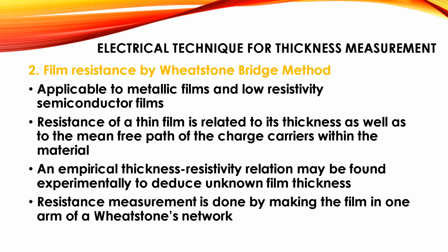The next method used as an electrical technique for thickness measurement is the film resistance by Wheatstone's bridge method. It is applicable to metallic films and low resistivity semiconductor films. The resistance of a thin film is related to its thickness as well as to the mean free path of charge carriers within the material. An empirical thickness-resistivity relation may be found experimentally to deduce unknown film thickness.